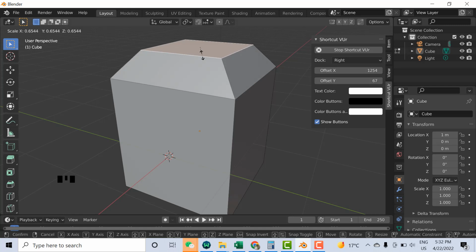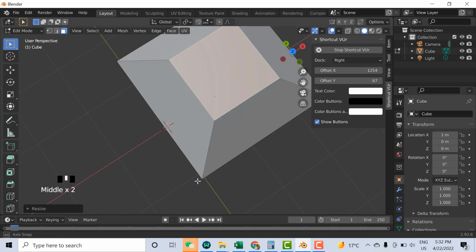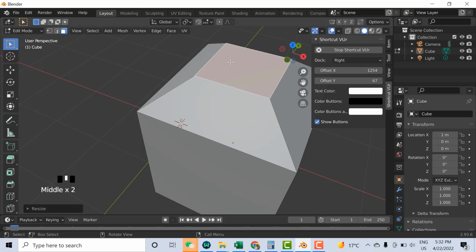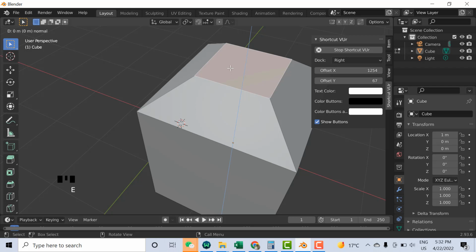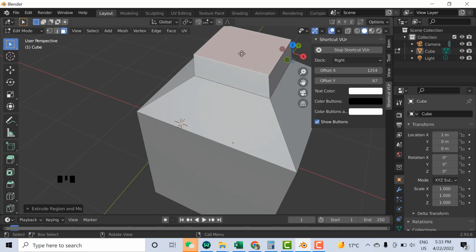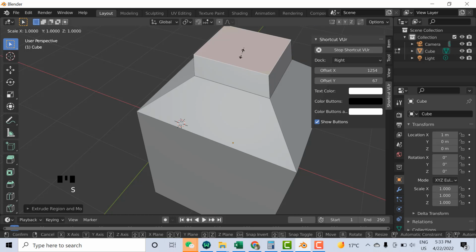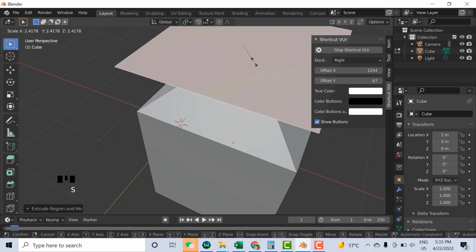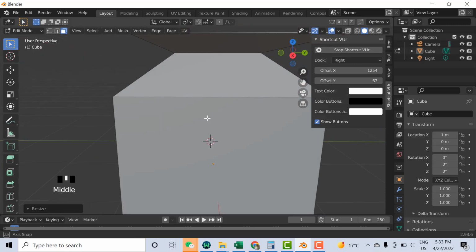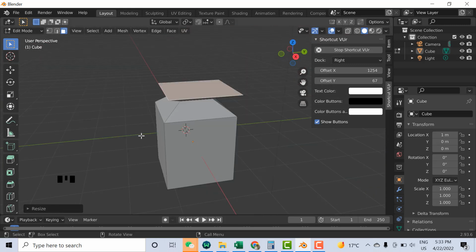For example, you want to make the top of a building or something. You don't need to move your original vertices or shapes. So here you see this seems good, right? So if I want to make this again, press E and move towards the Z direction, just go up. And now I scale again. Now you can see it's just going to scale the new part that you added here. That was the scale face.